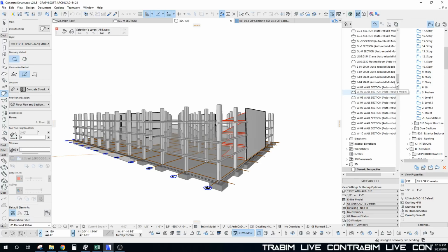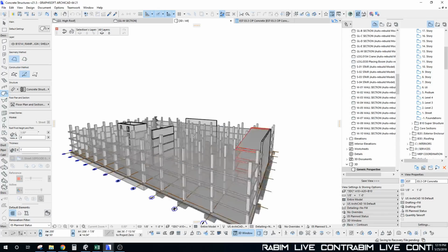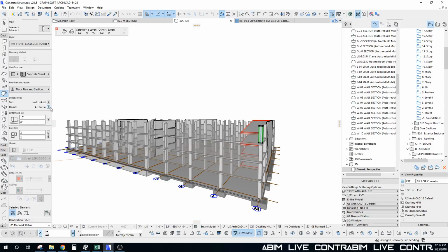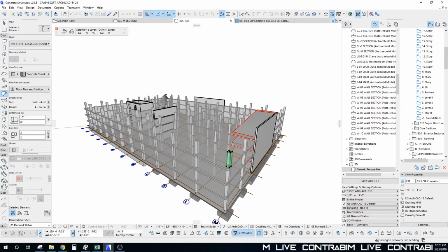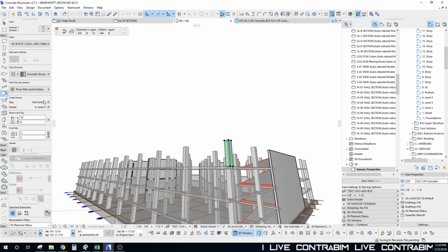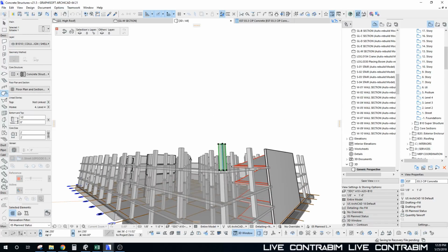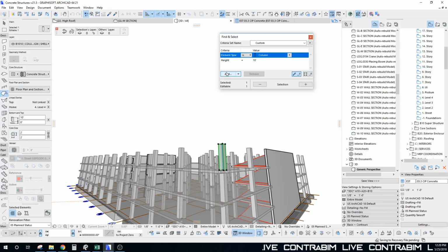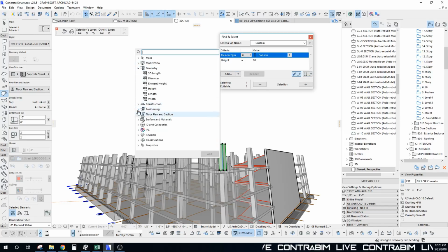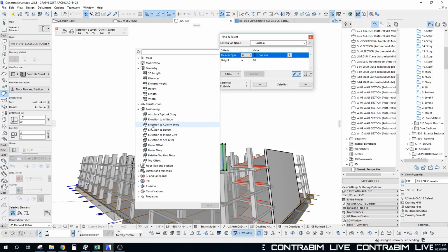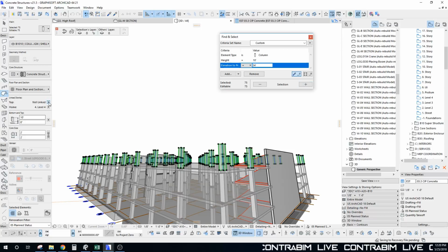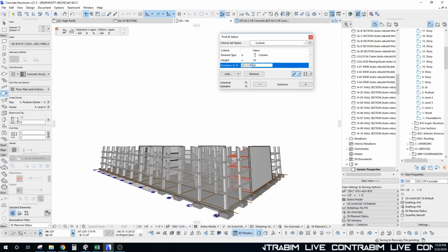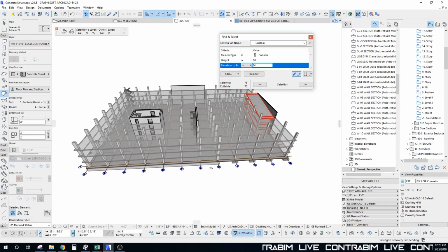We have all of our stories. All these elements are on our level 4. And I don't think they're linked right now because they didn't have a story on top of them. So we can come in here, add one more for position, elevation to project 0. And we can grab all those and we can just link them to our podium. So, okay, there we go.